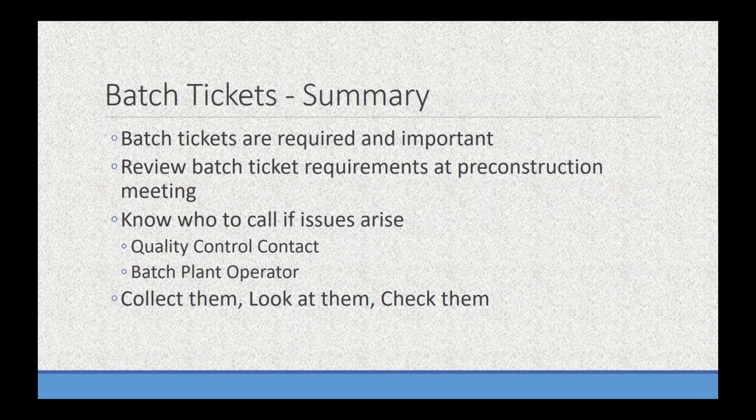The nice thing is the Appleton Tech Center, at least for our area, has a list of quality control contacts for some of the main suppliers in the area. So I reference that quite a bit. I print it out, keep that with me on the job site. And then just kind of an overall theme, we should be collecting the full batch ticket. We need to look at them and we need to be checking them to ensure that the concrete being delivered meets Spec 4.